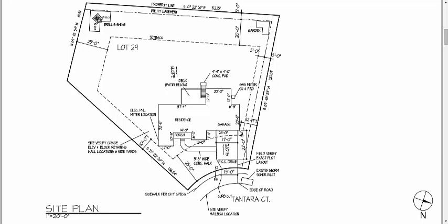This side over here, the closest thing is the garage. If you look at that point right there, 10 feet is that dash line, so we're a little bit further, exactly 2 feet 9 inches farther away from that setback right there. So our house is located correctly, or it's within its limits in terms of what the setbacks and the easements are. Like I said earlier, we could have taken this house and moved it clear back in this location right here. And that would have been fine.